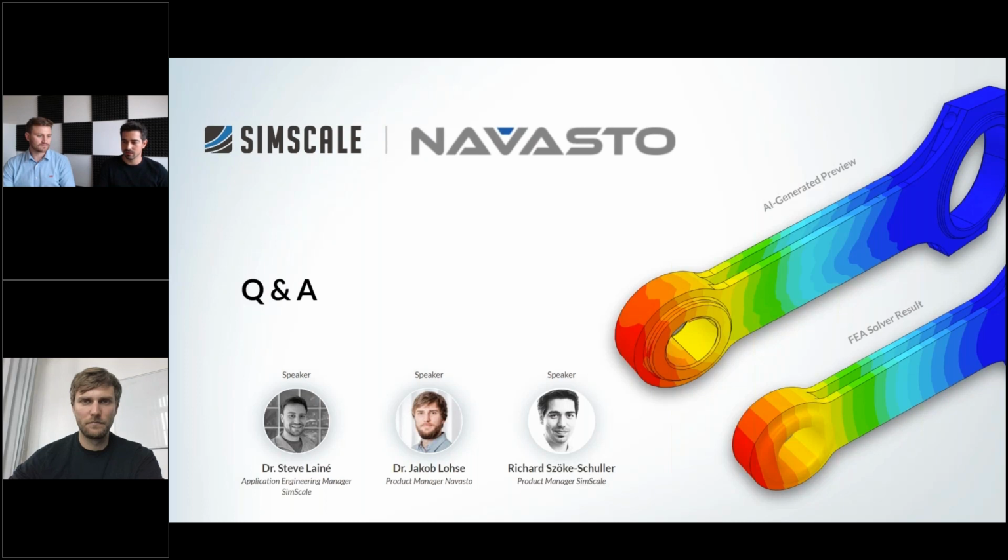Yeah, first of all, it's vastly different how many models are needed, how many data points are needed to predict. I think maybe Jakob can talk about that in more detail. The connecting rod was a very simple model. We used less than 200 data points to train it. And it also depends on the range of values you want to train it for. If I want to train for arbitrary sets of boundary conditions, which might even not make any sense, I might need to add more data to the problem to also capture these senseless scenarios. But the more defined my problem is, the less data I need to get to the same level of quality in the results.